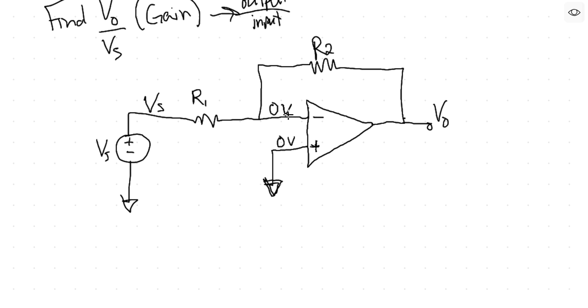All right, so that's step 1 of our node voltage method. We've identified all the nodes and we gave the nodes a name. Step 2 is identify the junctions where current is changing or potentially changing, and we're going to make a circle around that. It turns out that current actually isn't changing here, but it looks like it might, and so I'm just going to make a KCL here, Kirchhoff's current law.